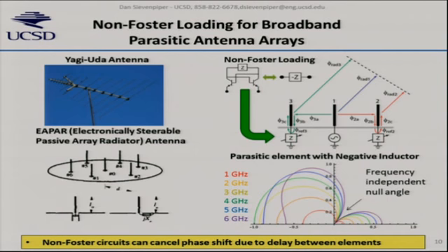Well, if these were non-Foster circuits, in fact they can. Think of a small shorted transmission line as similar to an inductance. Well, a negative inductance would look like a small shorted transmission line of negative length.